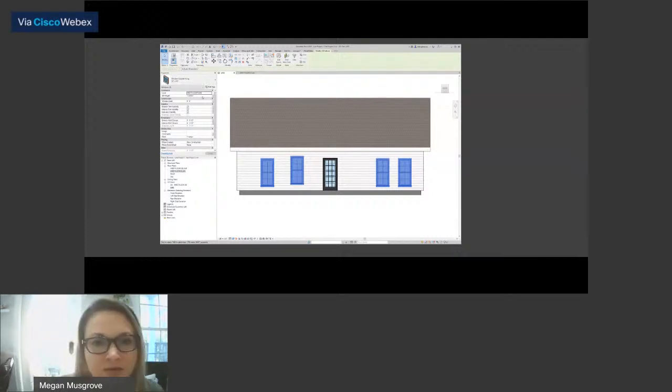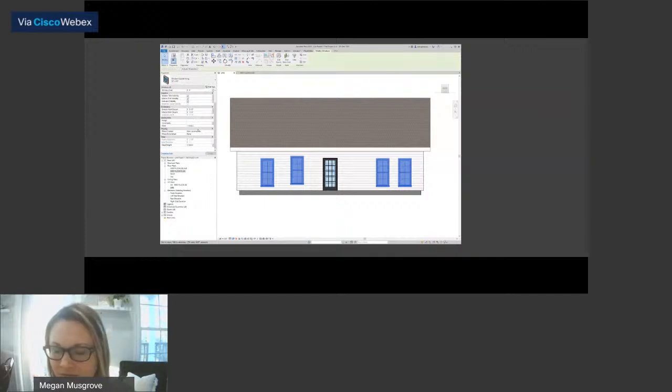Again, difference in releases. In Revit 2021 and older versions, over here we would have the head height. Oh, no, we still have it down at the bottom. Okay, I feel like things are rearranged and I'm lost. But okay, we have a head height. I was thinking it wasn't there. We can do by sill height or we can do by head height. I usually do by head height because that is what I put in my window schedule.